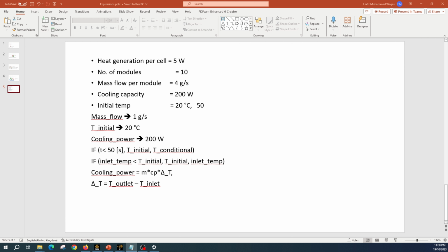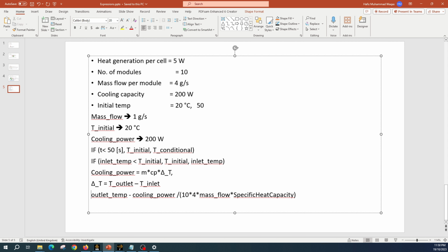So what is that equation? That's here. Let's call it inlet temperature. Here is cooling power, and everything mCp will come into the denominator. So you can see mCp has come into the denominator. Here is cooling power, and then delta T, so we have separated inlet and outlet. So q over mCp, and outlet temperature. So here is the delta T.